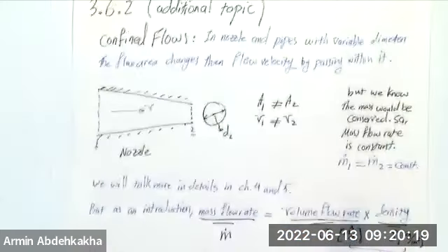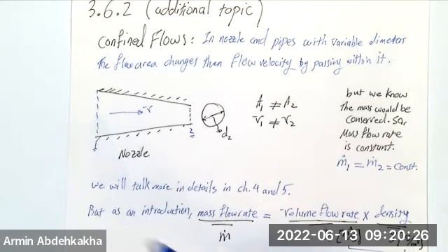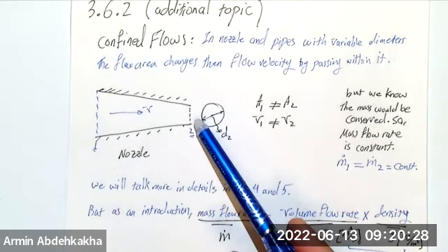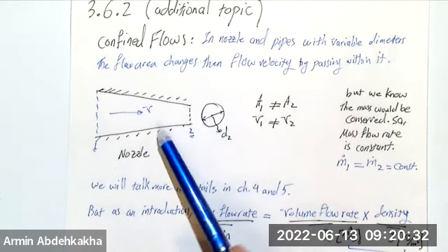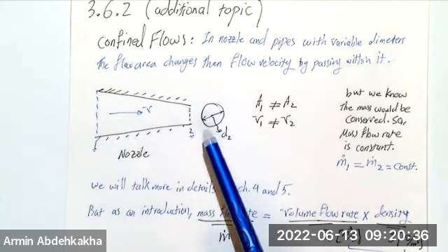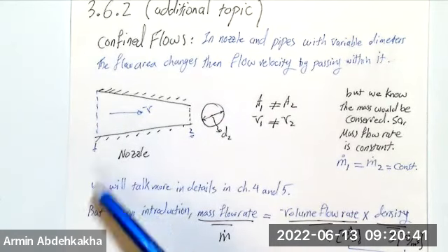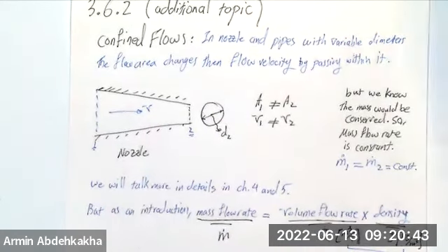Let's come back in here. You put the Pitot tube test here. You get the velocity at point 1. How can you calculate the velocity at point 2? If you know the diameter or area at point 1 and point 2, and you measure the velocity at point 1, and you can assume that for most fluids rho is constant, right?